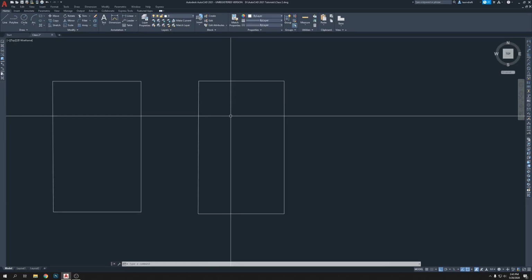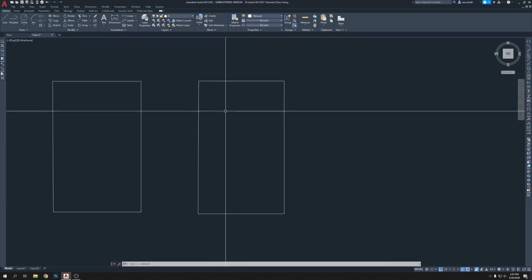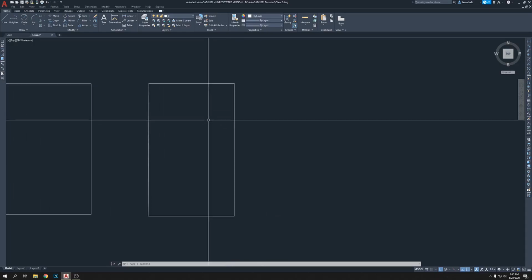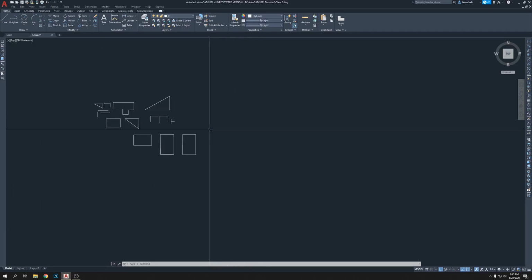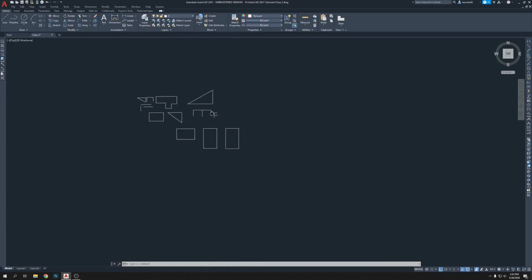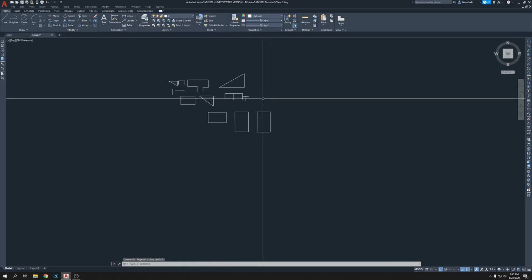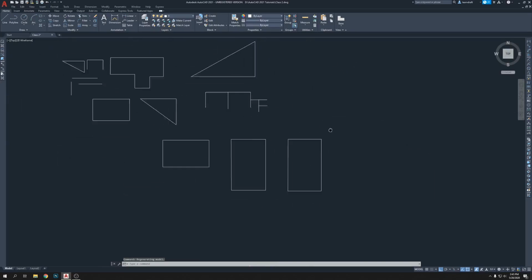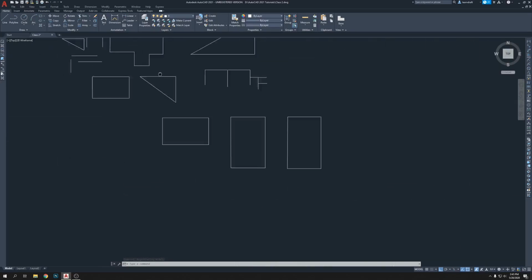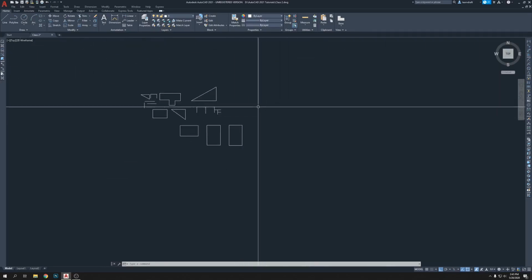So what else is left? We're gonna draw a stair with the line. If you want to draw a stair, you need to use the dimension, otherwise it's gonna look ugly. I'm actually panning around with my middle mouse button, so you need to practice it a little bit like this. You push it this way, push it this way, and it's gonna stay with you.